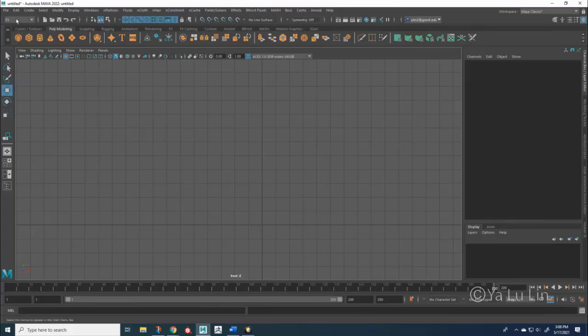Okay. Now the second line here is your status bar. The status bar contains your new scene, open scene, save scene, redo, undo, and your hierarchy, your object mode, your component mode. And this is some of your components. By default, this small window is closed. You can click on this triangle to expand those selected elements.